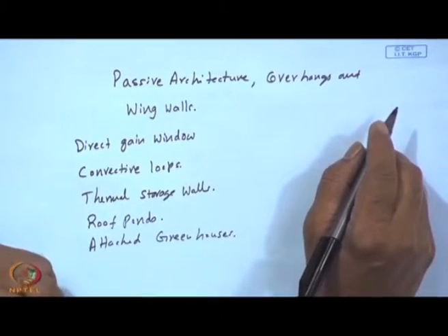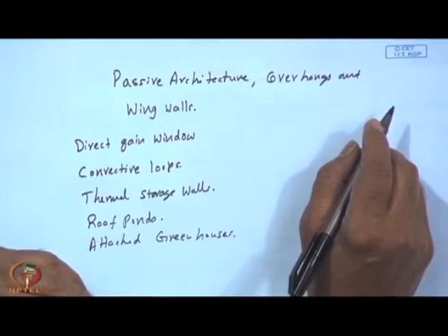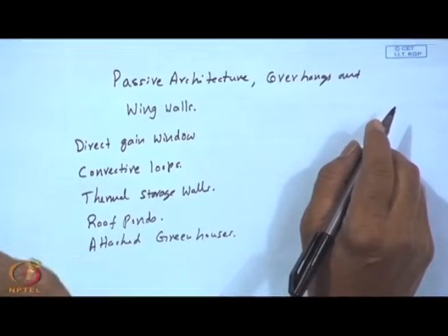The solar radiation entering into the greenhouse through the glasses will be re-emitted at a longer wavelength. Consequently, it will not escape, and the window glass has the property that it allows the solar radiation at a lower wavelength, but shall not allow the longer wavelength radiation to escape. Hence, the enclosure will be hotter or warmer.